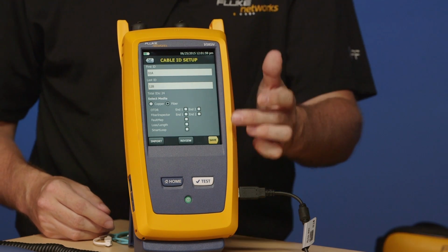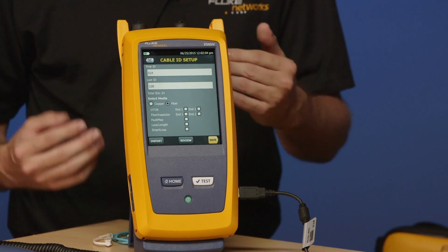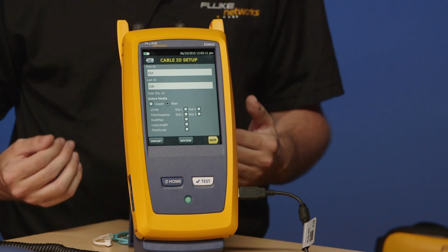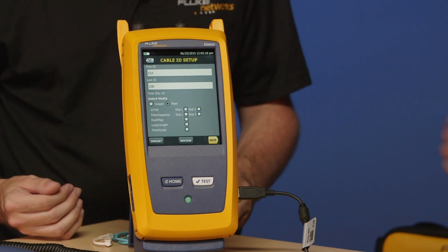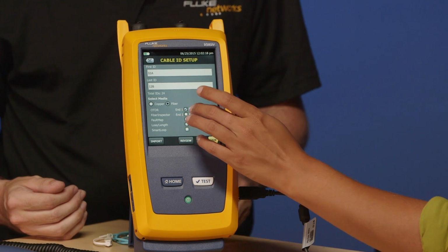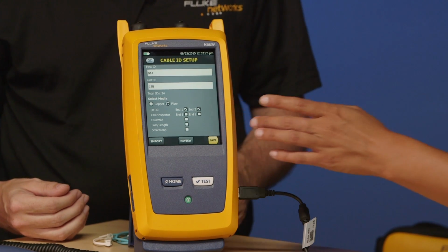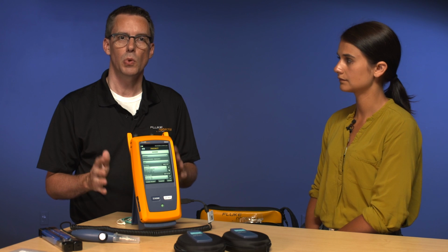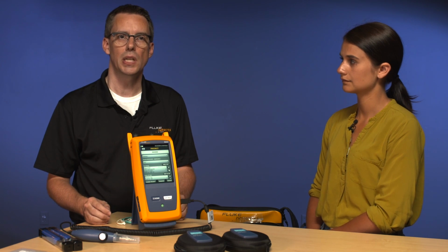Excellent. Now, you'll also see that we get to choose what sort of test we want those assigned to. And we're doing an OTDR test today, and when you look at the OTDR, you'll see it says N1 and N2. We're going to do a fully standards compliant measurement. We are going to be measuring both directions. So go ahead and tap N1 and N2 on the boxes there. And then once we've done that, we'll go ahead and tap Save. That's our OTDR setup with our cable IDs and our test limits. In the next video, I'm going to show you how to set a launch compensation and do a successful OTDR measurement.